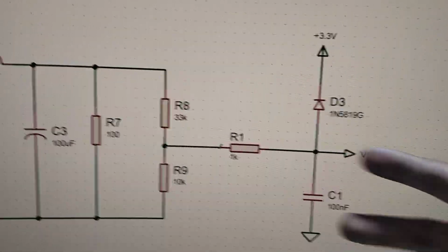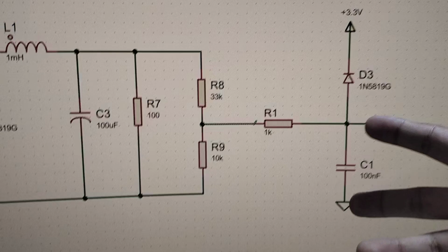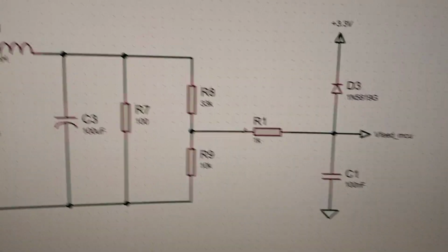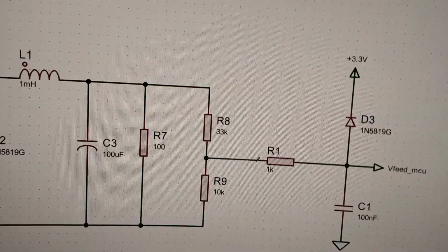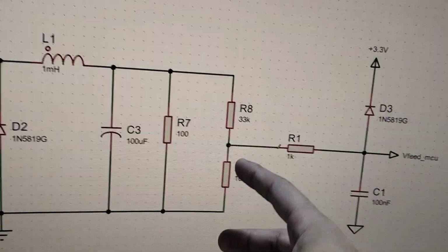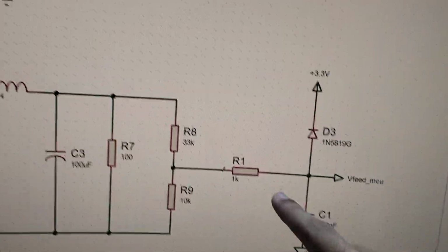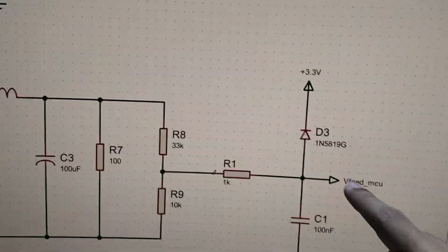We know the ADC can't handle more than 3.3 and somehow maybe 5 volts, right? It will basically just get fried and your entire board will go for a toss. So you need to protect that, and that's exactly why this clamping diode exists. And what that basically does is, somehow if the voltage across this gets above this point, right? So this point is where your voltage across this comes, this node.